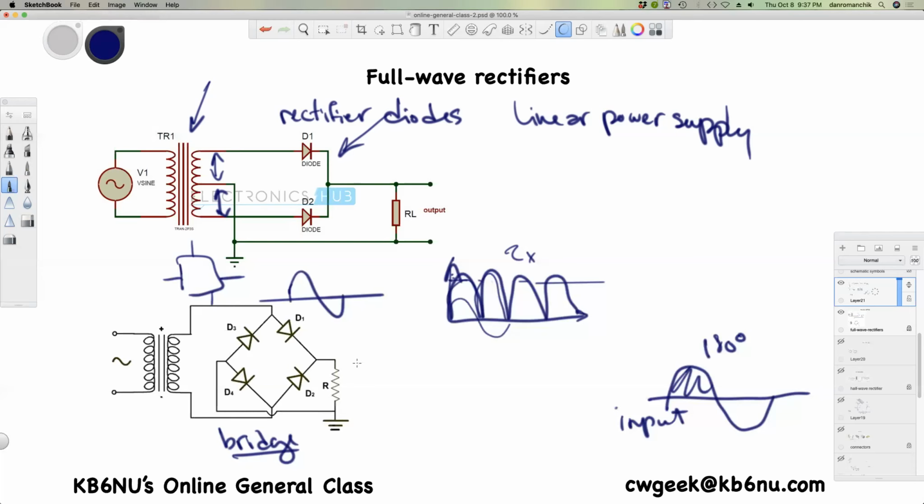And so I'm guessing that if you use a full wave rectifier, you have to use a filter, right? Because it's going to be twice the frequency of the AC signal, correct? You have to use what now? Filter. Oh yeah, in fact, that's the next section here. And then if you use a half wave rectifier, you don't have to use a filter because it's going to maintain the frequency. Oh no! You still have to. In fact, you have to use more filtering if you use the half wave rectifier.